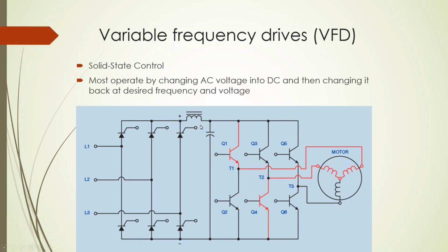The second stage is the filter, and that's this inductor and this capacitor. And here we're filtering the ripple out of the pulsing DC to turn it into DC voltage. And then here we have our H bridge. And these solid state devices are going to turn on and off in different pulses. Now, these pulses are going to be full voltage pulse, then off. Using pulse width modulation, we'll then develop our rotating field for the motor. So here, in this third section, we're actually going to be recreating a sine wave using a mathematical function of integration.